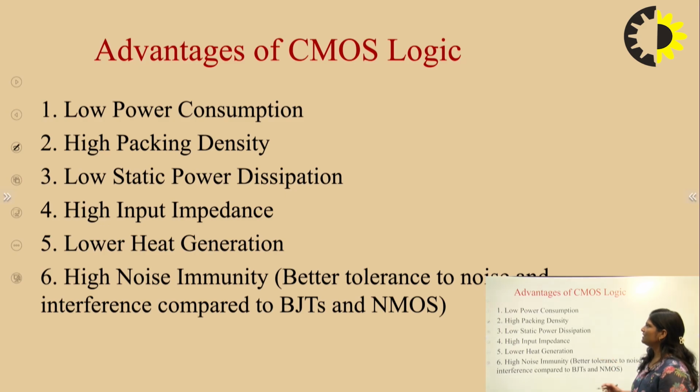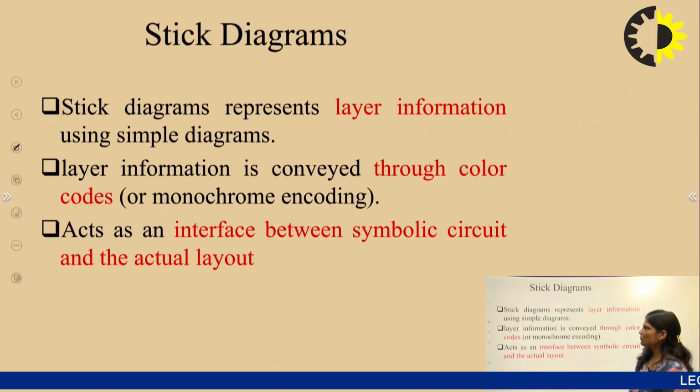Now these are the advantages of CMOS logic: low power consumption, high packaging density, low static power dissipation, high input impedance, lower heat generation, high noise immunity. So these are the advantages of CMOS logic. Now we have to proceed to the stick diagram.